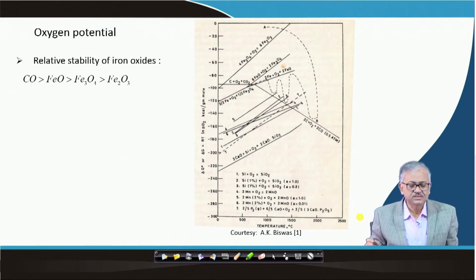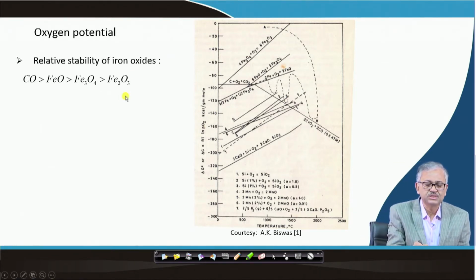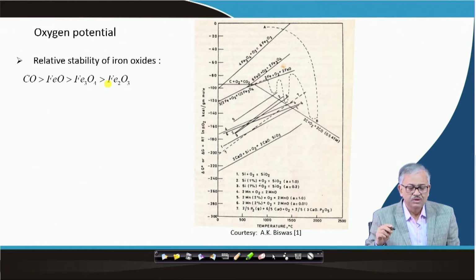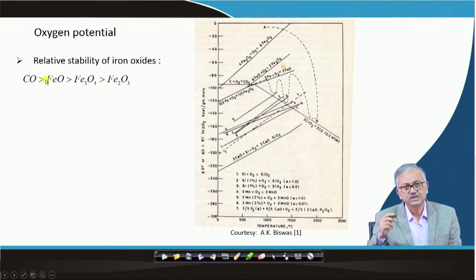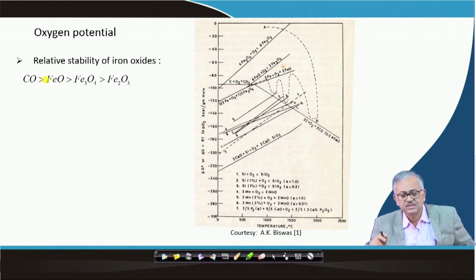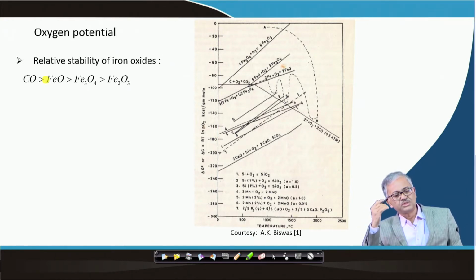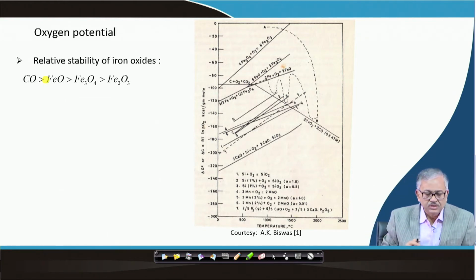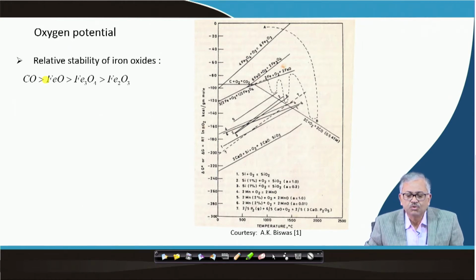But even with the lower reduction potential, you can easily reduce Fe2O3 to Fe3O4, and even Fe3O4 can be reduced to FeO, but FeO is quite stable and requires a little higher reduction potential. So, it will be reduced in the lower part, in the middle of the furnace. Okay. So, that we have seen, that is the reactions: in the top part Fe2O3 gets reduced to Fe3O4 and then Fe3O4 is reduced to FeO, and then a little lower FeO gets reduced to Fe. Okay.